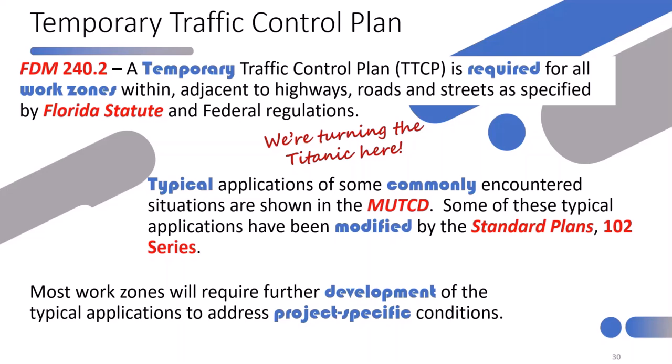Temporary traffic control plans are required for work zones that are adjacent to highways, and that's in Florida state law as well as in federal regulations. And as you know, there are commonly encountered situations that are covered by details in the MUTCD.